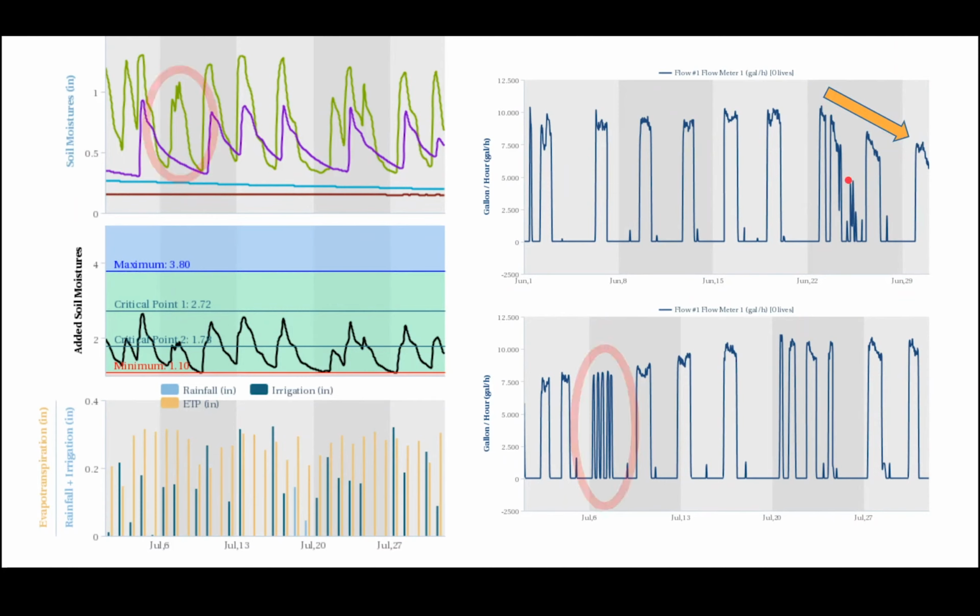And in a desperate attempt at solving it, he did pulse irrigation and ran it 4 times in a day, which doesn't really help, because those pulse irrigations keep the water shallow, not deeper. And we ended up finding that the flushing valve was stuck open. So he was losing a good percentage of his water through the flushing valve, like 30–40% of the water was going back into the reservoir.